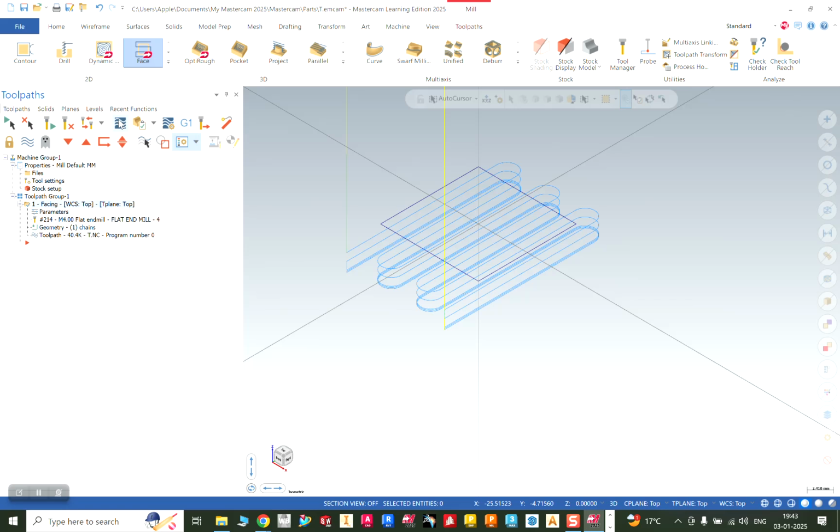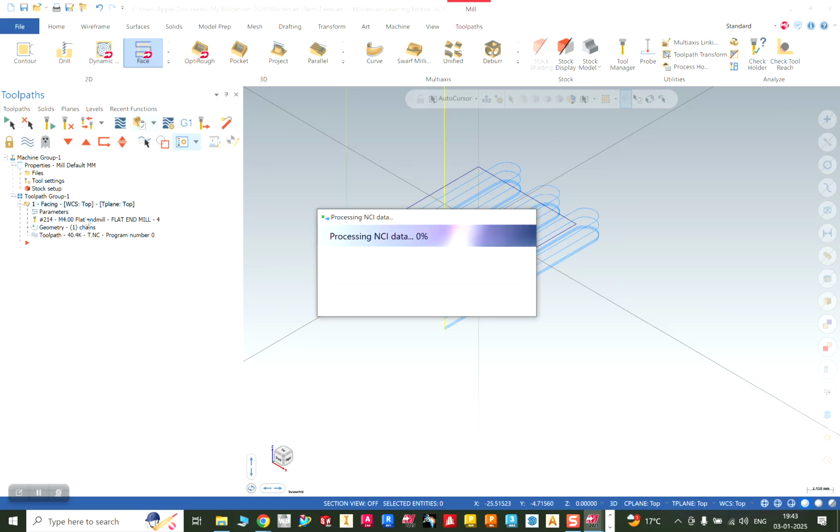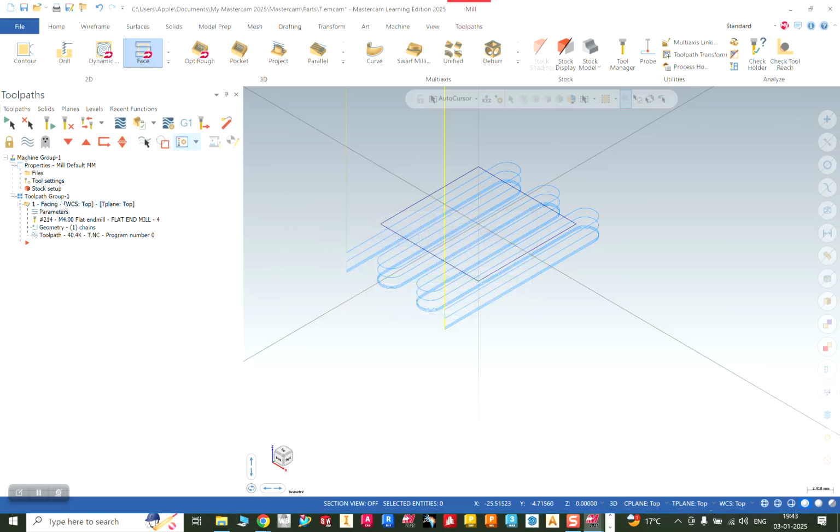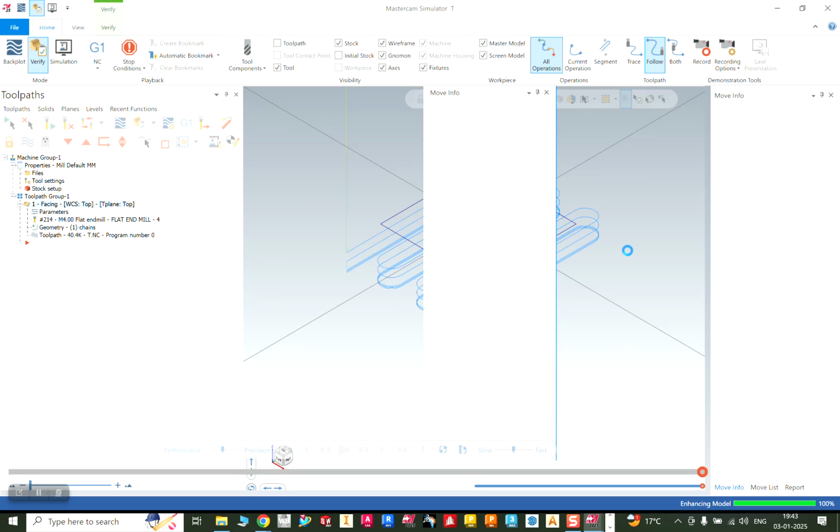In 2D you will not see the material cutting over there, it will be only in 2D. I'll show you that part in the next class. Before that we are only going to verify. Verify means you will move to the 3D machining. You just need to click here, and if you have done anything wrong during the machine selections, an error is going to come.